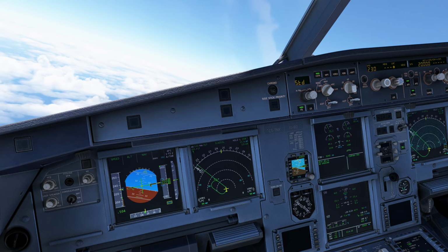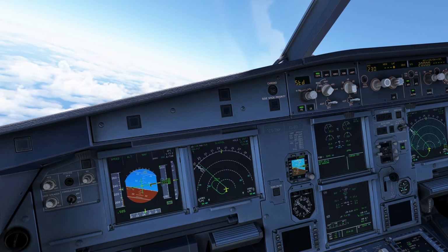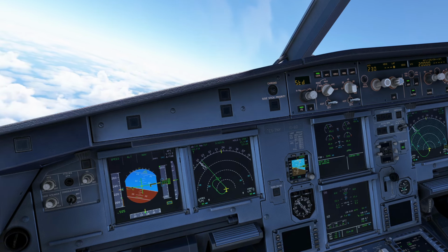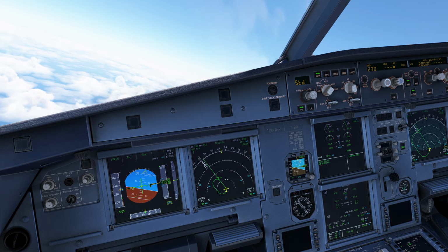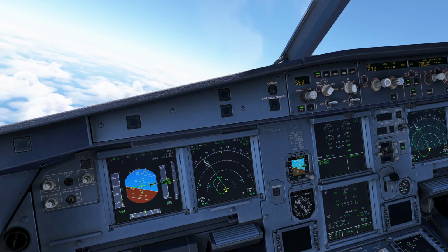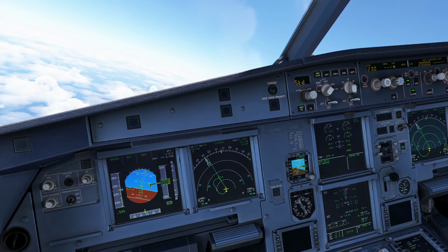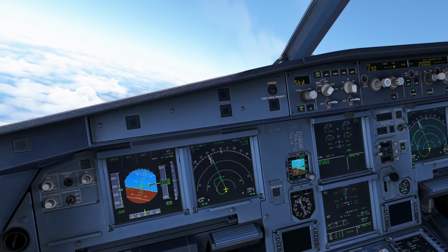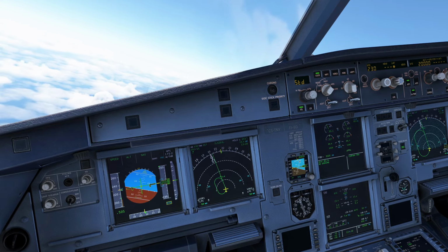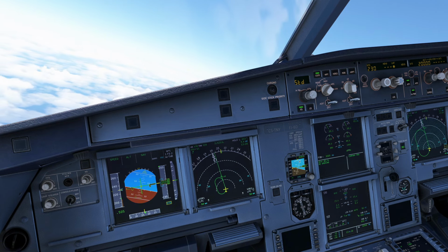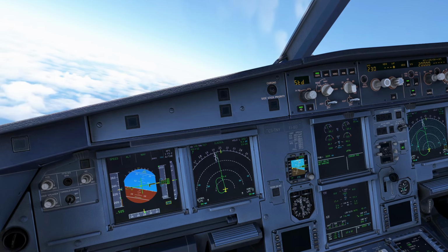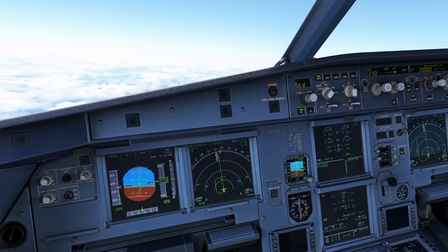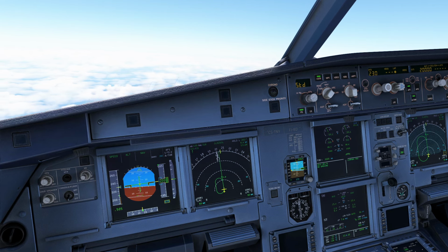And today we are maintaining flight level 200 in a hold just before approach to Golf Charlie Lima Papa, Gran Canaria Airport. As instructed by ATC, we are on hold at flight level 200, and we are going to have a full brief and a detailed review of two kinds of approach technique which are recommended by Airbus according to some